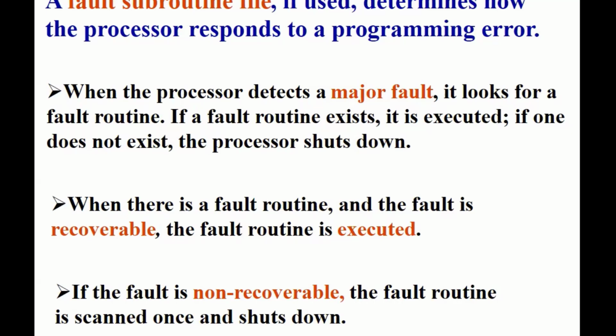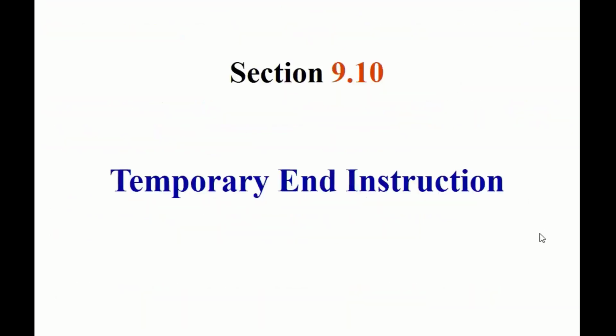You might have seen when you're doing this, it's almost like overriding that fault. If you've had a chance, it usually happens with hardware. When you're trying to download something to hardware that is faulted, it gives you a caution and it says you want to write this and override the fault, or you want to log or inspect that fault.